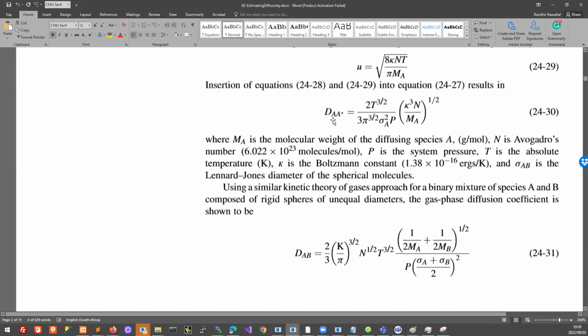That's one summarized way of looking at it. We always think of diffusivity as a kind of binary thing, A diffusing against something else. In this case, it's A diffusing against a whole mixture. Quite often we do it on the pure component basis, so A diffusing against some specific B. So there is some mixture diffusivity, A against a whole mixture, and if we have diffusivities of A against each of the species in the mixture, then there are so-called mixing rules that help us translate that into the mixture diffusivity or the effective diffusivity.